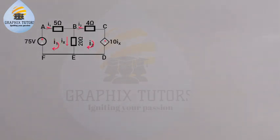Now if you apply your junction rule, which is KCL, Kirchhoff's current law, at node B here, you discover that I1 is going in, so I'll call it positive. I2 is going out, I'm going to call it negative. I3 is going out also, negative.